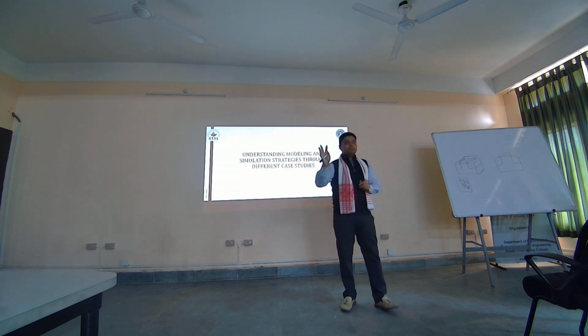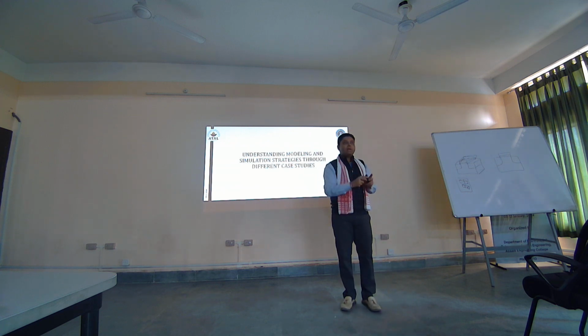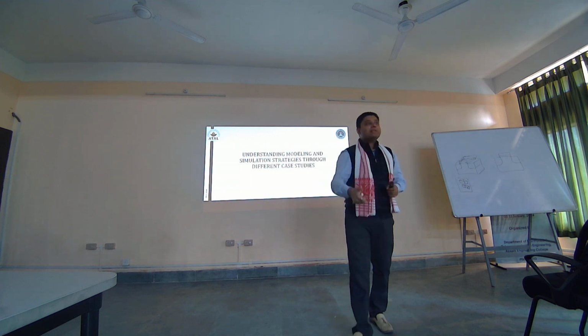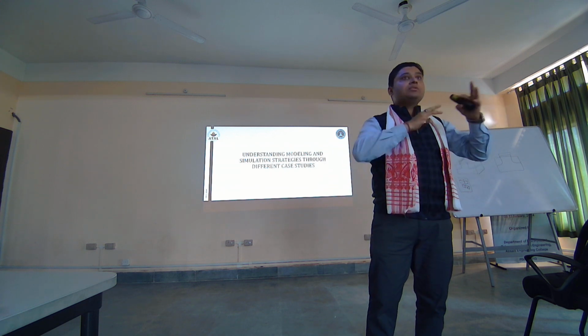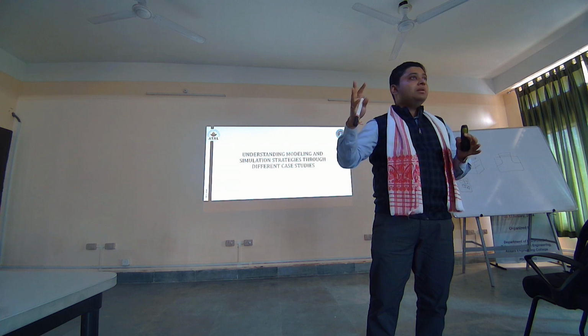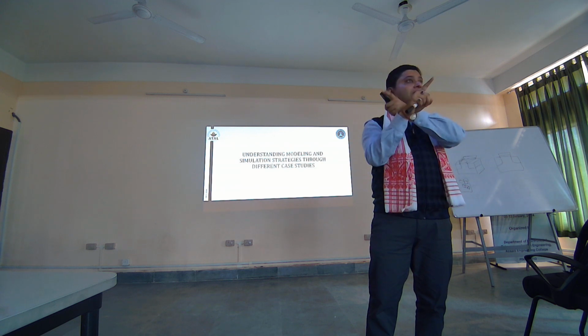Now it has never ever happened that one model is going to satisfy the entire performance of your device. I'm talking about simulation. Okay, in an industrial simulator, whenever we start, we always try to go with the maximum number of physics-based models. Okay, but now the problem there is if you are going with the maximum number of physics-based models and you are simply randomly inserting them, some of them may be conflicting with one another.